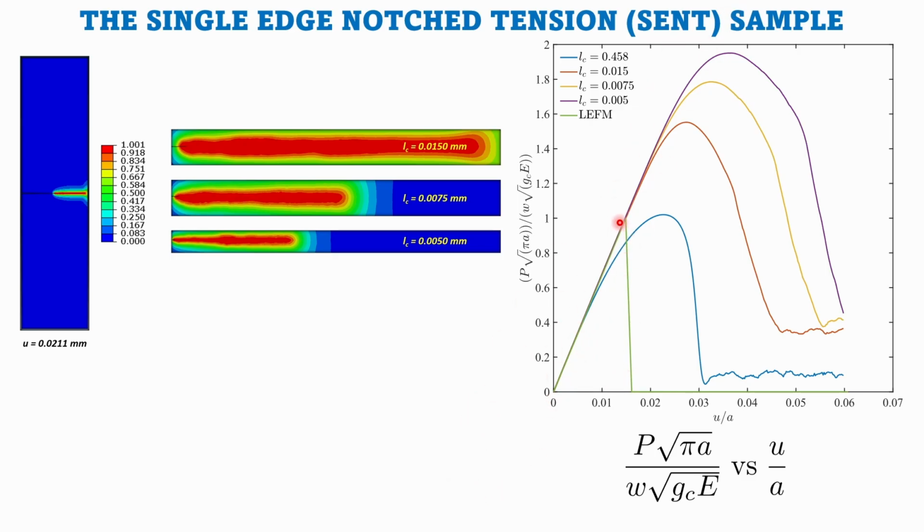So this green curve, we have to cut it somewhere in order for the crack to grow. Correct? So we cut it at PC. Okay? So essentially, when P is equal to PC, this quantity is 1. You can find out how.